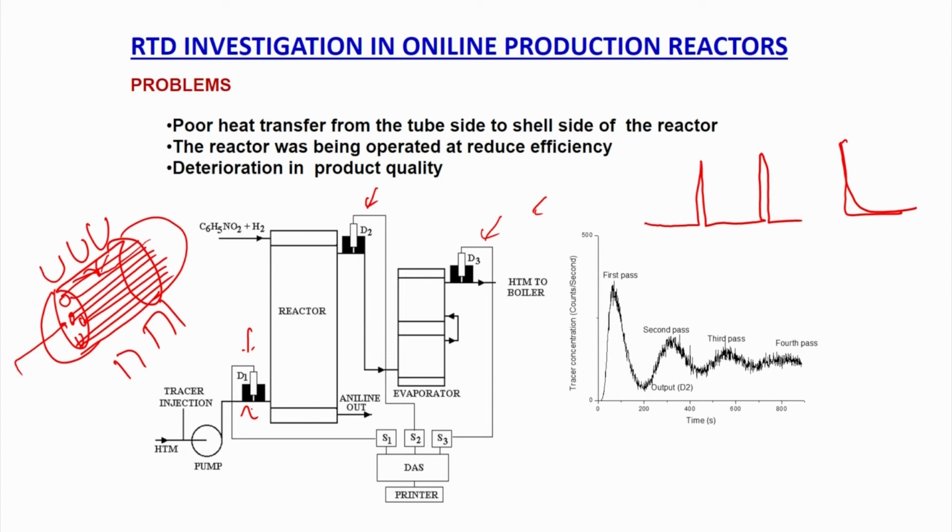Again, a chemical tracer cannot be used, because suppose you are using a heat exchanger and you want to find a leak with a chemical tracer, then you have to insert a probe inside to see where the pH or conductivity of the liquid is changing. Similar thing, suppose I have a pipeline and I want to find the velocity, say in crude oil transportation. I discussed in the measurement techniques that in crude oil transportation, because of wax formation, any single phase flow measurement devices like Venturi, pitot or rotameter cannot be used, because they will choke immediately.